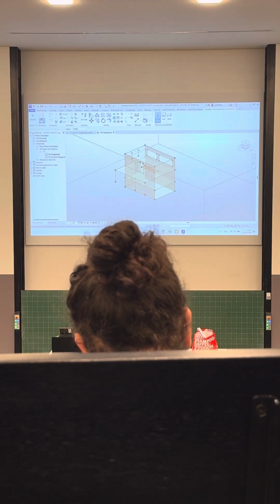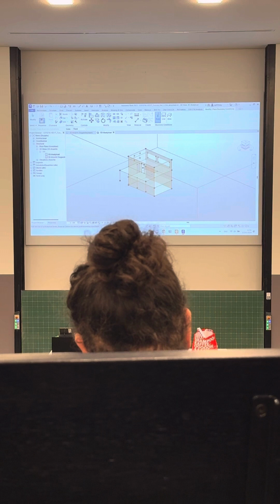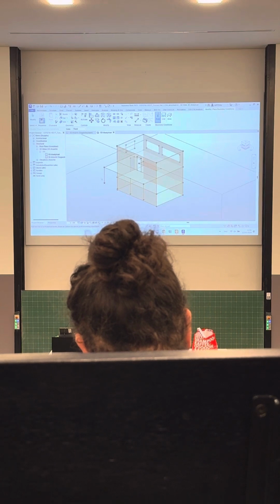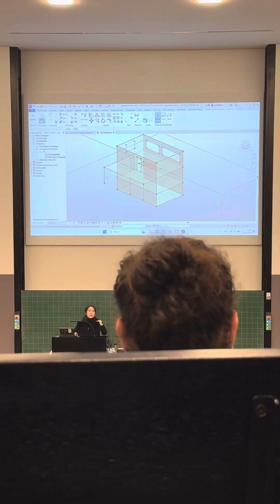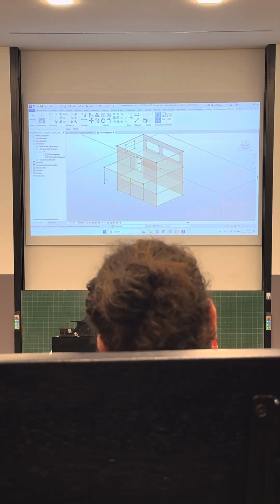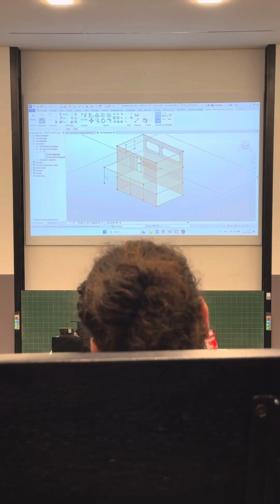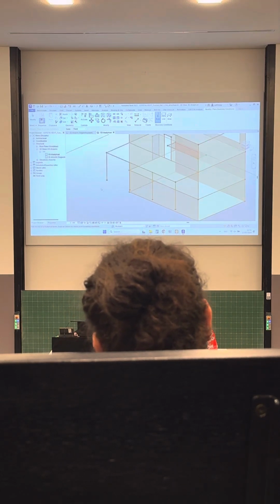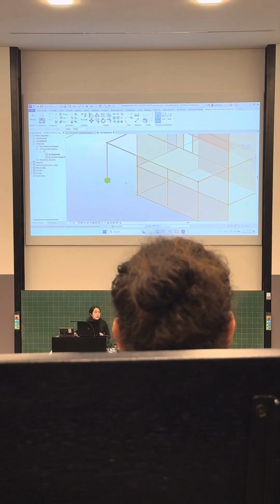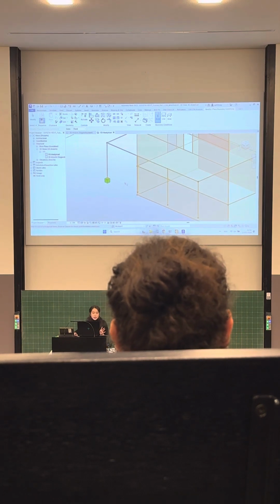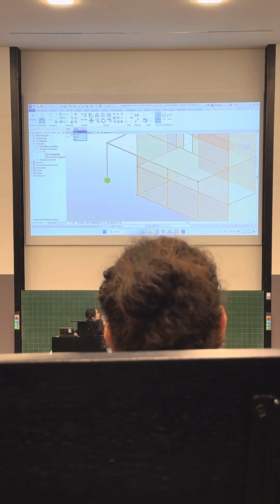You will need different ones depending on your models. For example, as I said before, I did not take into account the pinpoint foundation because I want to design it in another software and I just need forces from the big model. So here I can simplify and put just a point support that is fixed. At least this is what I need for me.